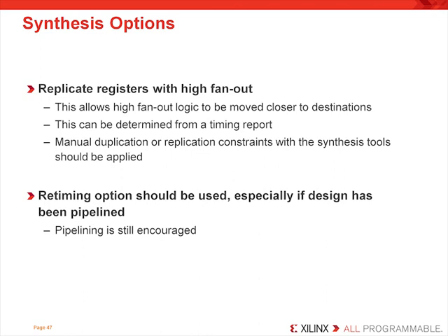I have had many customers ask what maximum fan-out to set their synthesis tool. In fact, the choice of setting values depends on how far you are from meeting your timing objectives and do you have sufficient resources left available. So keep in mind that if you have a high fan-out secondary control signal you're generating, to try and anticipate the fan-out and duplicate the logic at least once.